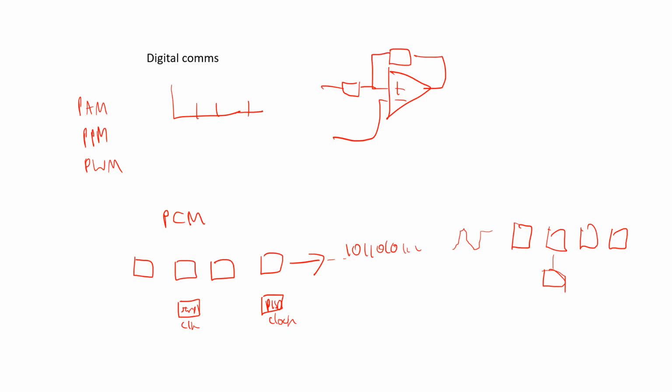If you don't have negative feedback, the gain will be 100,000. So the output will saturate positive or negative. If that's V in and that's 0 volts, this one particular one here would be a non-inverting. And then how to work the resistors out. Remember, you just draw them out like that. We know we've got 0 volts in the middle.